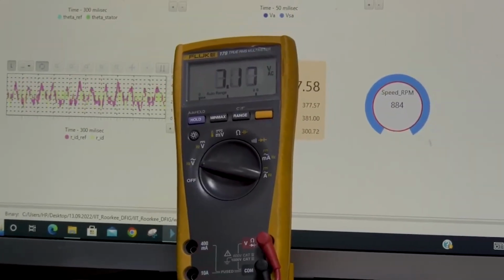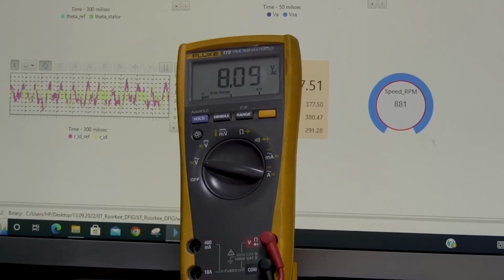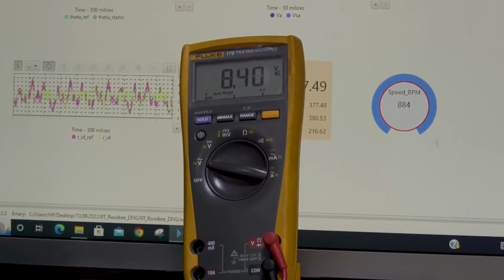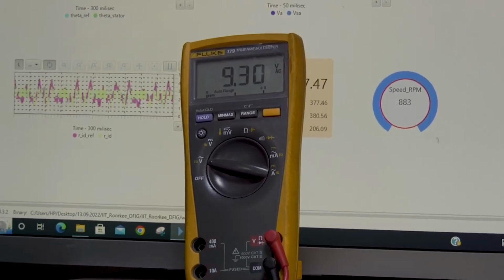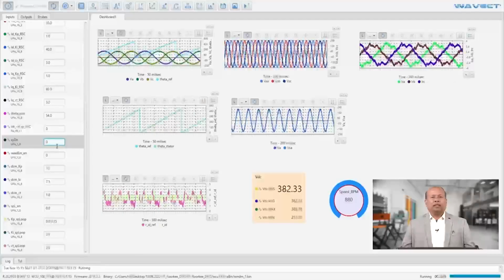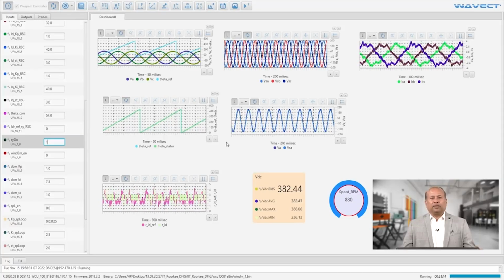After the voltage gets matched in the software, we check the contactor of the grid side and stator side and ensure that the voltage across the contactor in the multimeter is less than 20 volt. Here we are getting a value of less than 10 volt across all three phases. By ensuring the voltage is less than that, the contactor connecting the stator and the grid connection is closed, and then the synchronization is done by enabling sync done in the software simultaneously.